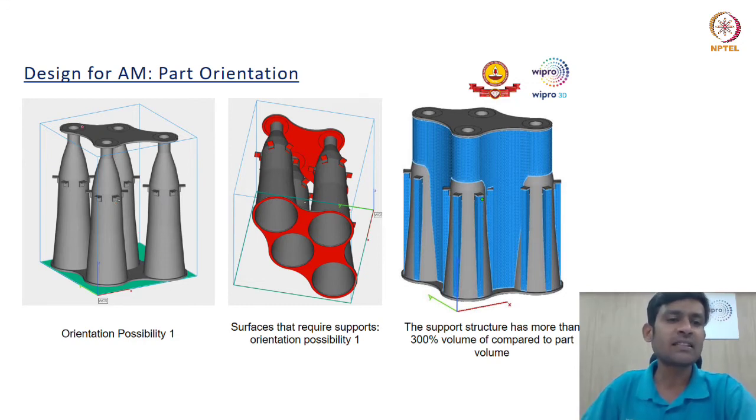The build chamber that you see here belongs to the EOS M290, where we have a build volume of 250 x 250 x 330 mm. Basically it is 350 mm, but certain space is occupied by the thickness of the build plate at the bottom in the Z height.